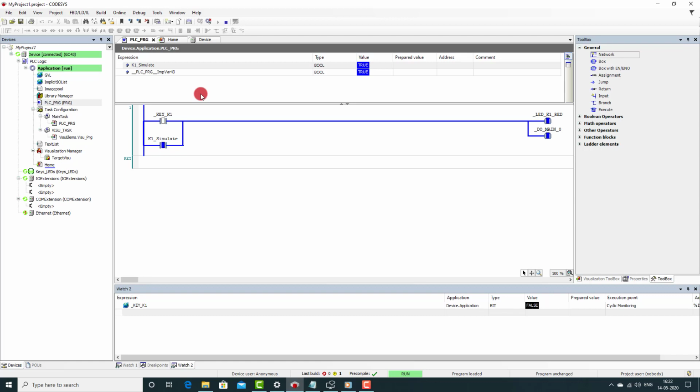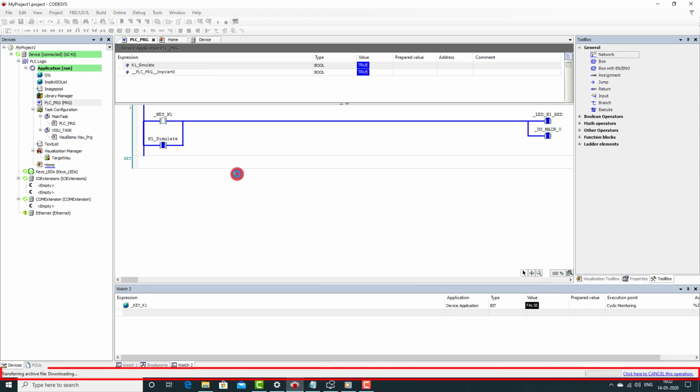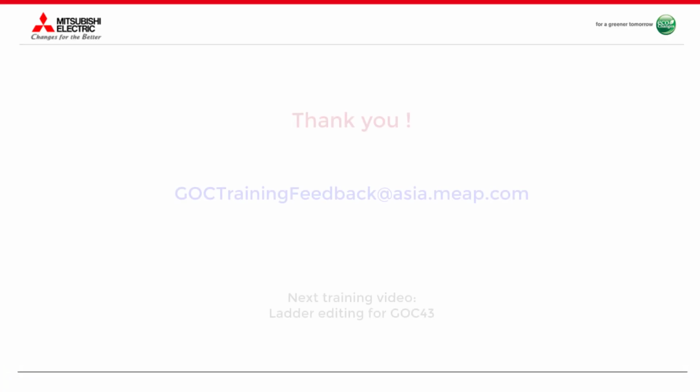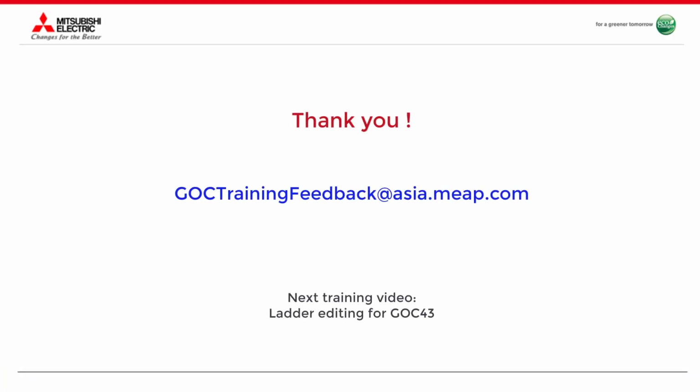Source code will contain all comments and variable names in the project along with all application data including images in the HMI application and user management data in the project. Execute the command Source Download to Connected Devices to download source code. Download progress is displayed on the status bar. That's all about the introduction to CODESYS.